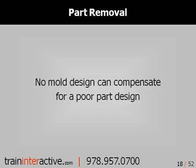In reality, plastic parts are getting more complicated every day, but keep this point in mind. No mold design will ever compensate for a poor part design. Even though this seems obvious, we see hundreds of parts designed without consideration of how they will be injection molded in production. So when a part's not designed properly, we're forced to try to compensate through processing. And this usually leads to longer cycle times, compromises in part quality, just to ensure the part will eject properly. And this also takes away from how the mold will run in production.